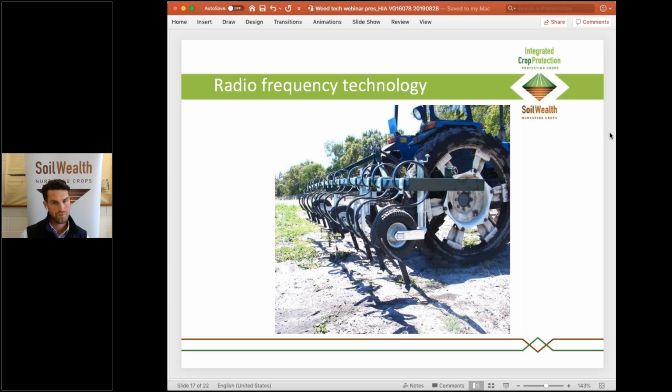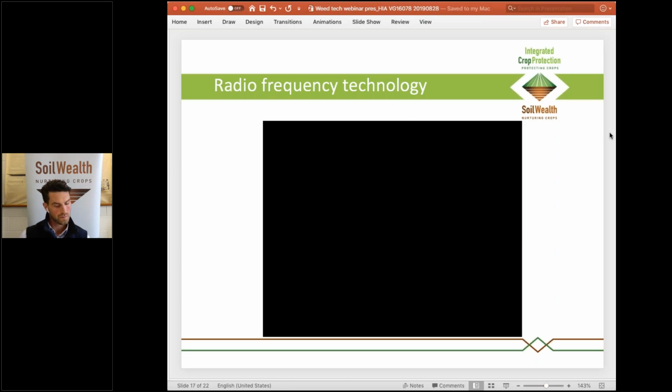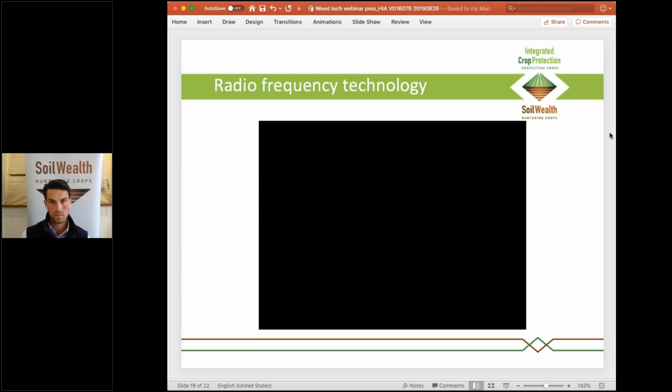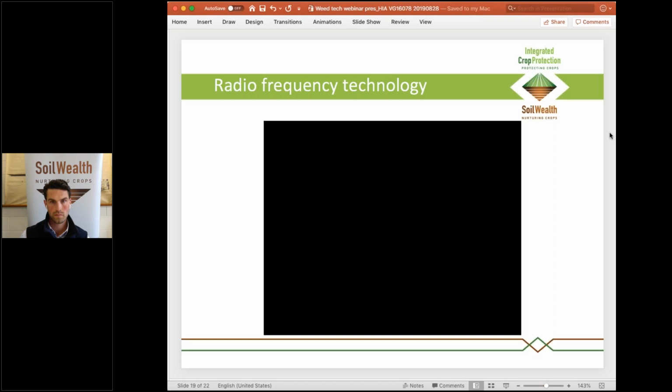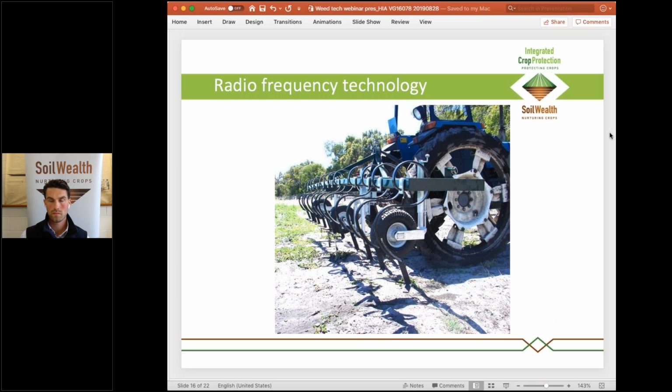Yep. You can see on the right-hand side there, the crop's been mechanically weeded. That's about 8 kilometres an hour that was done at. And we got very good weed control. The reason for the speed, you need the speed, the accuracy and the repeatability. The speed gives you some sort of movement sideways, which buries the weeds in the crop row itself.